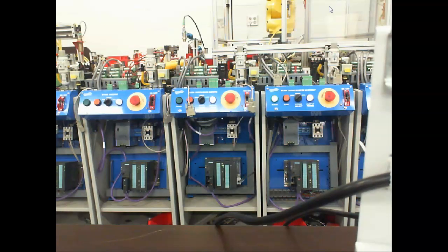This is a big advantage: if we've got a PLC that fails, we don't have to have a spare PLC for every module of a manufacturing line. We can just bring in a new PLC, wire it up, and these PLCs now are made to wire real fast. In the old days, they weren't. Then swap it out, put the right program in there, and then we're up and running.